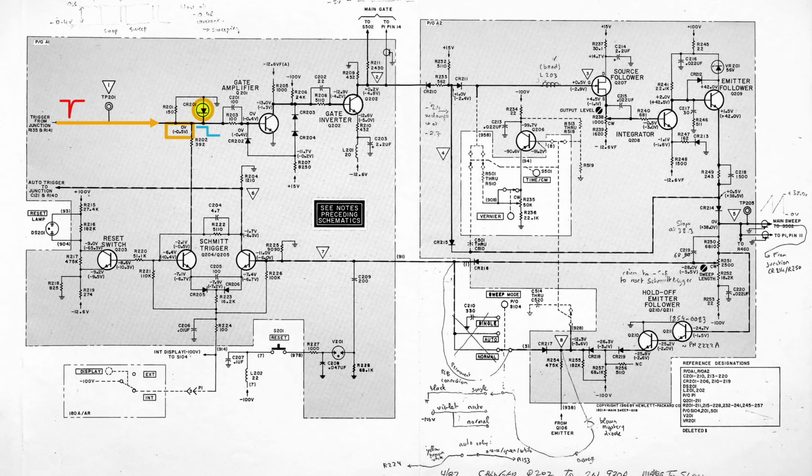Most likely we don't see it because the loop feedback from the Schmitt trigger is wrong and our tunnel diode is not biased properly to exhibit its bistable behavior. At least that's my working assumption right now.